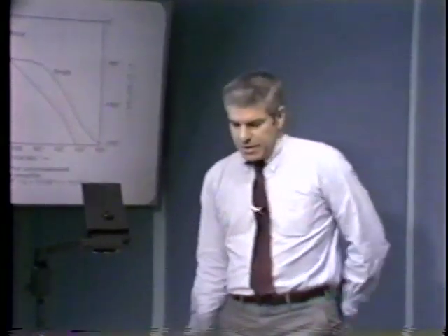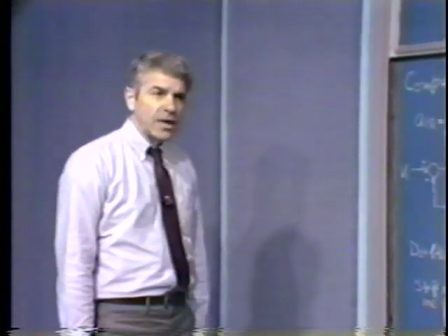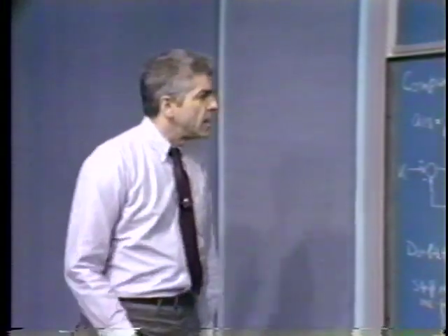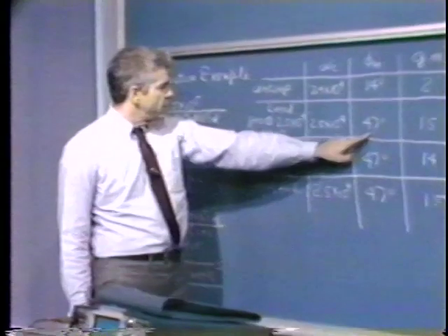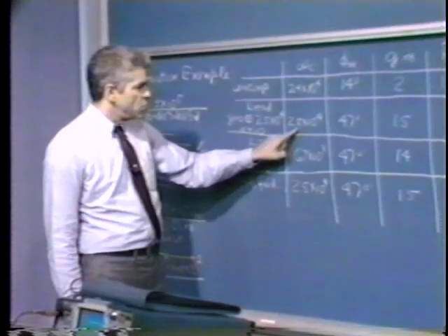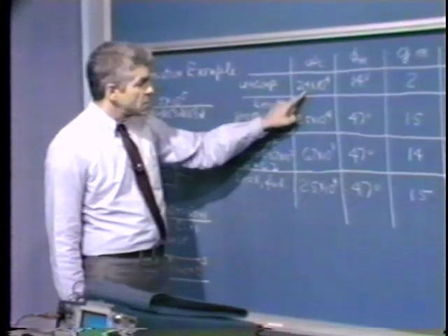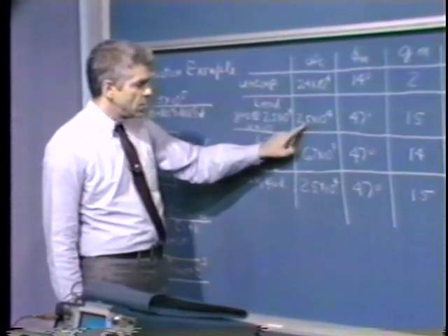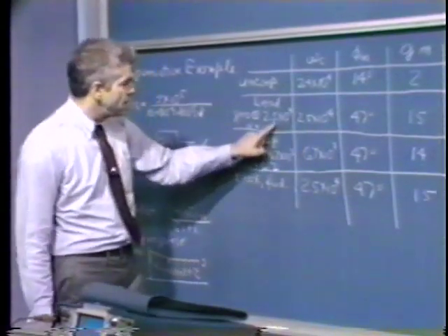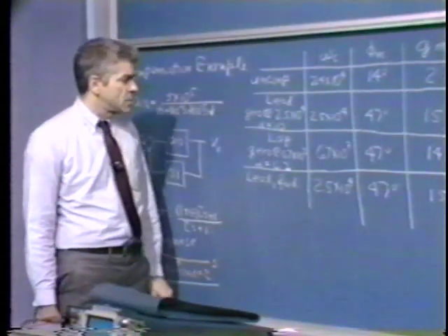When we do that, we find out that our maximum positive phase shift combines with the phase shift associated with the amplifier itself, with the original A of S, and we find that we're able to get a phase margin of about 47 degrees. Crossover frequency with that combination is about 2.5 times 10 to the 4th radians per second. We increase crossover frequency just a bit by adding the 0 close to crossover. In fact, the 0 location in our lead network comes out just about at the compensated crossover frequency of the system. We can look at that Bode plot.